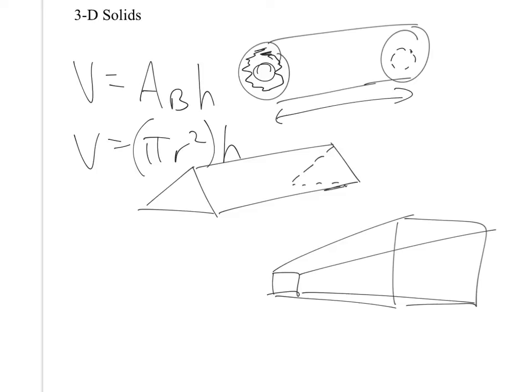What else? Okay, so great examples of these. This radiator is not a good example, but some radiators have what are called pin fins that come off the end of them. And they're literally cylindrical shaped objects coming off the end. They allow to increase surface area so that the convection can occur more efficiently. The more surface area, the more convection you have, the more heat can heat up the room.